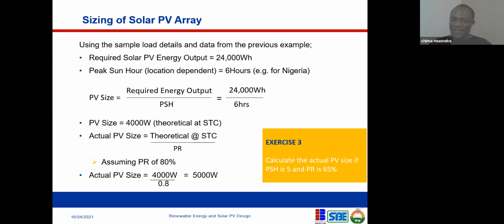If for example you have 6 PV modules that you want to connect, and each of them is 12 volts, you will connect 2 in series, 2 in series, 2 in series. So you have 3 series connections, right? Then you connect those 3 series in parallel. If you connect them in parallel, your voltage will remain 24, but your amperage will increase.